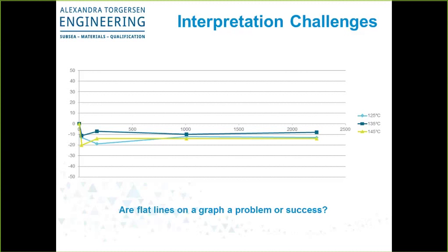And for a steady degradation, this is great. You just have to keep in mind that if you are dealing with materials that will have abrupt degradations like chemical changes, fatigue issues that happen relatively suddenly, then you can't extrapolate beyond where you've tested, or you need to understand the degradation mechanism on a chemical level to claim life, because this type of testing doesn't really go beyond the last data point at 13 weeks.